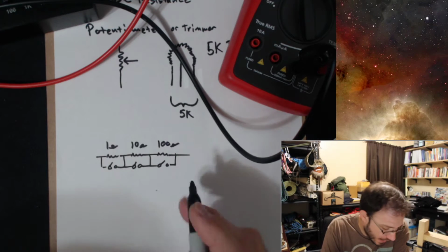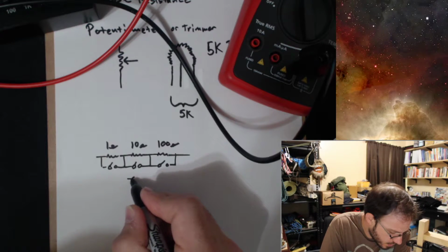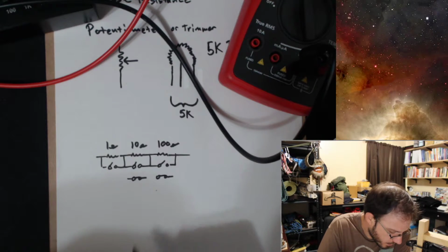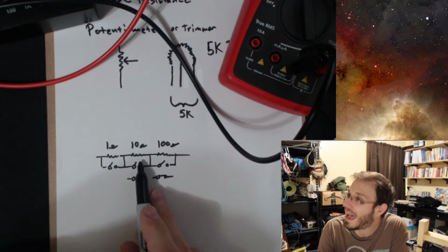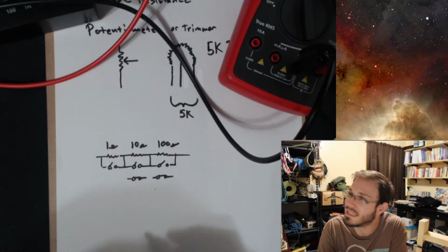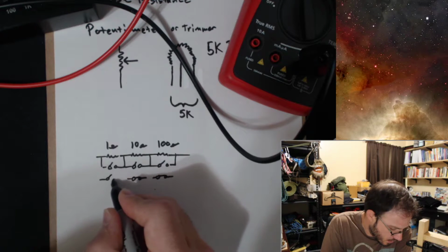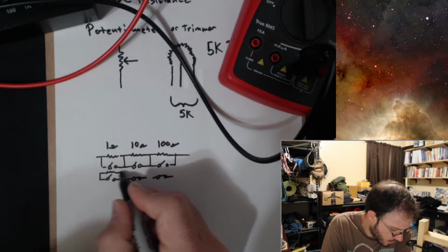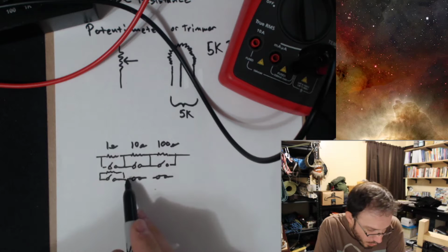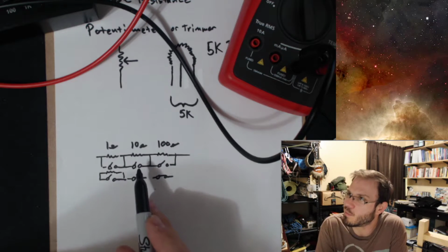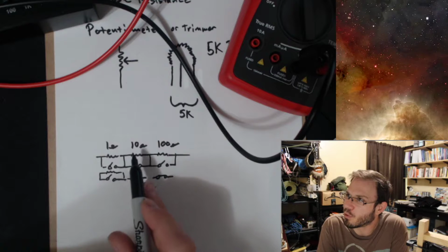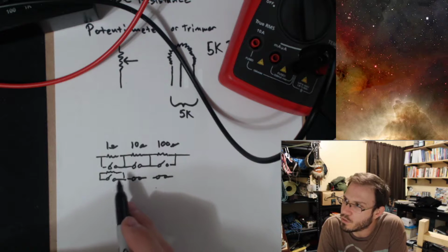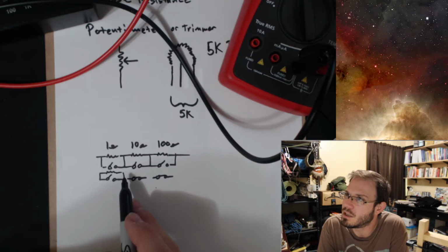The switch being down is actually all of these being closed, and so I'm bypassing these 2 outermost resistances. When any one of these switches becomes closed, it shorts around this resistor, effectively removing it from the circuit. So that's what's going on inside of this resistance substitution box.